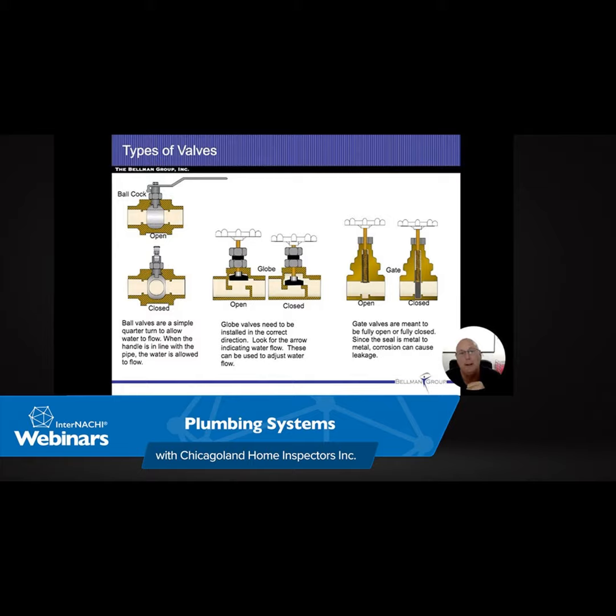So it actually has two purposes between the sink waste pipe and the soil pipe. That has a distinct name to it, and we're going to call it a wet vent. So it's designed to vent the toilet, let air come in there, break the siphon, but it still allows water from the sink to go ahead and go down there.